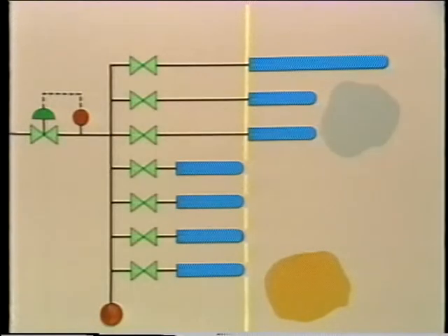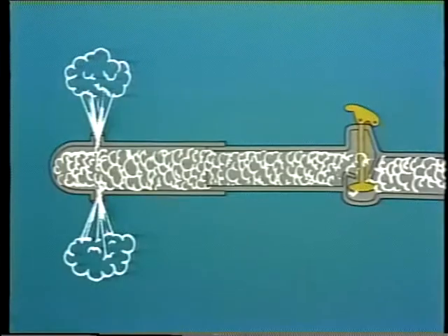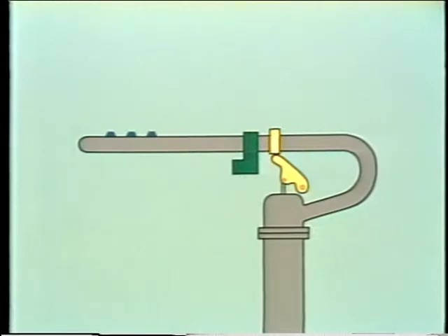And finally, we've seen the 3 types of soot blowers and how they fit into an integrated system on a boiler. These 3 types are fixed soot blowers, the simplest type that are economical to use where operating requirements permit, such as cooler passages in the boiler, rotating soot blowers, which are also used in cooler areas but blow larger areas clean, and retractable soot blowers, which are used where temperatures and the flow of hot gases would rapidly harm stationary elements.